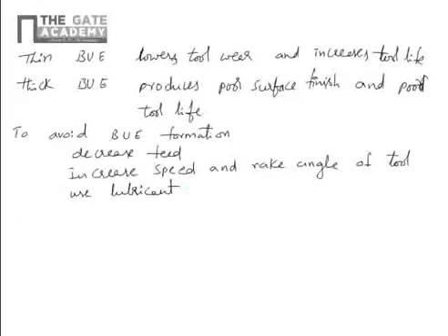So built-up edge formation takes place only with continuous chips, because in case of discontinuous chips, when the small chip is produced, immediately it is thrown out away from the metal cutting zone. Along with this, microchips are thrown away. Time available for welding is less.